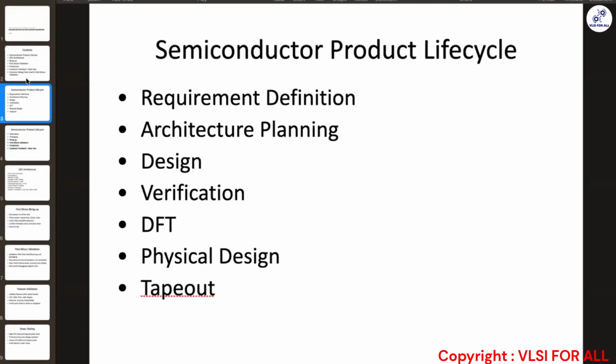In the designing phase, you write all the chip logic. How your particular chip should behave would be written in the designing phase. Consider that your USB 4 should go down when it goes to low power mode. You write it in such a way that whenever low power mode comes, your USB devices go down. Then if the signal comes up, you should be able to bring that IP back to the S0 state. Those things would be written in the designing phase.